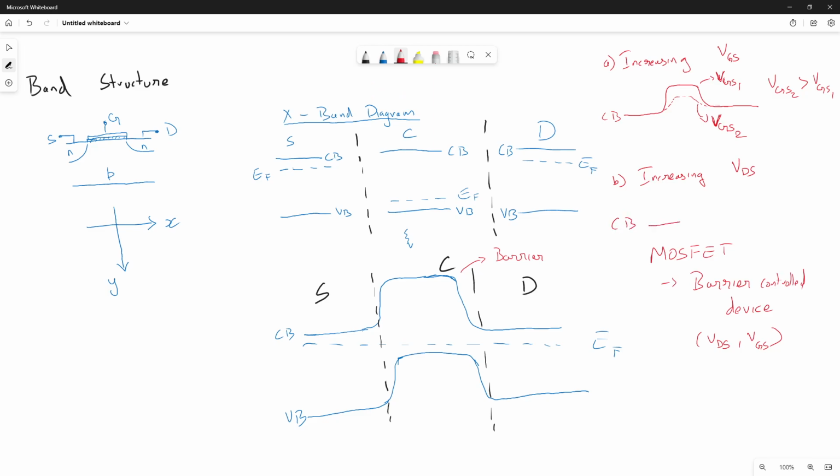So over here, let me draw this using dotted lines so that I can clearly show what is happening. As and when I'm increasing the drain voltage, this part will remain roughly the same, or at least I expect it to remain the same, because I'm only changing the source-drain voltage. I'm not changing the gate-source voltage. So this part of the barrier should remain roughly the same. But as I'm moving away, this energy will go below to whatever new level of VDS I have achieved. As I'm increasing it further, I should make it look as uniform as possible. Also, erase this.